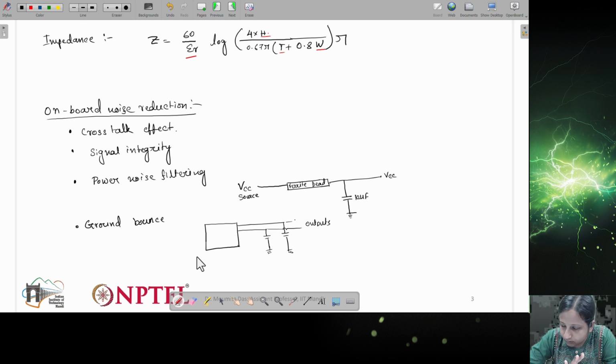Now as I mentioned, there can be impedances in the line which need termination. How is this impedance termination going to be done? If there is an impedance, we have to provide a matching impedance for the termination so that it can reduce the noises due to the impedance present. This impedance termination can be classified into different types.